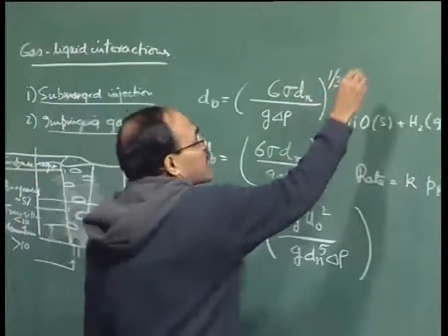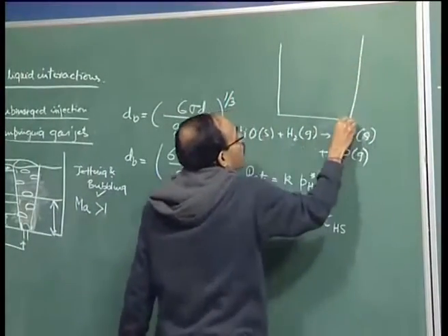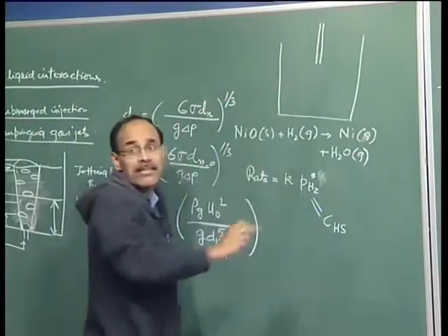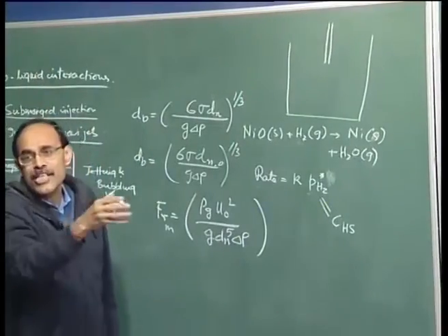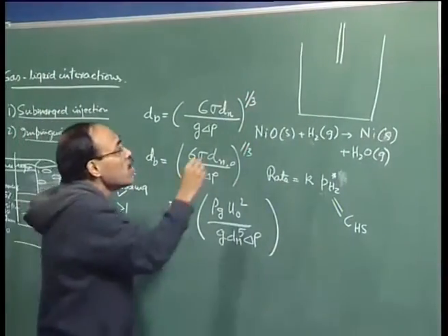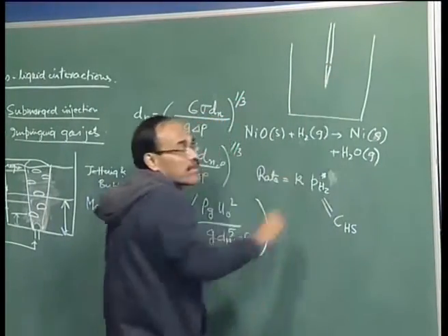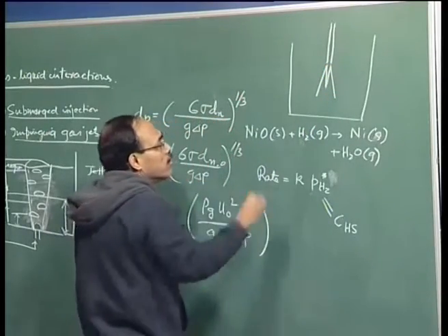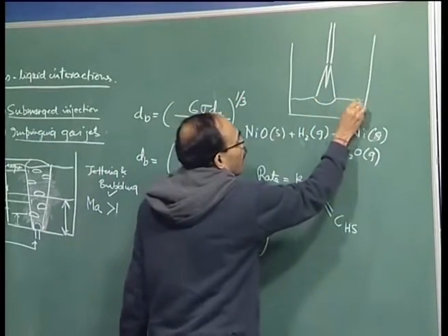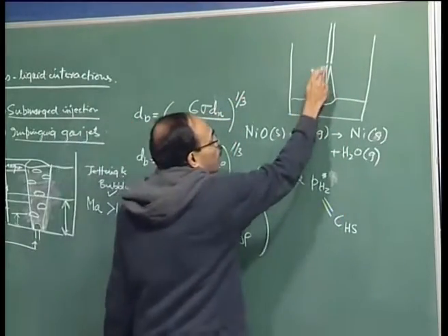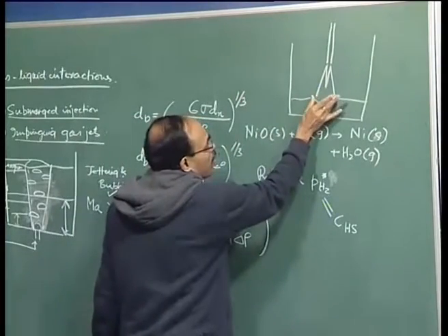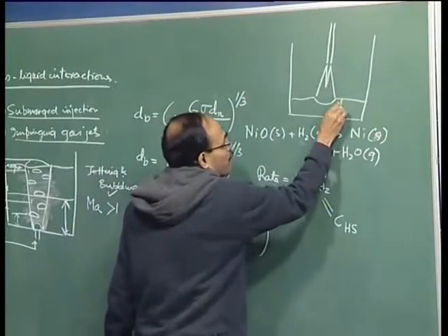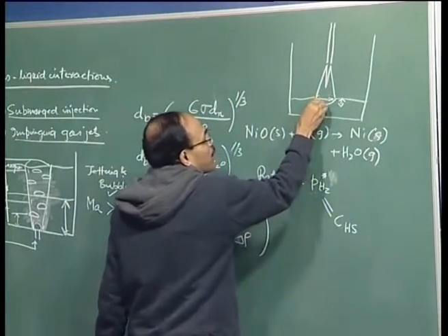Finally, very briefly, about the impinging gas jets. When you have impinging gas jets on a system, particularly an LD converter, you have different kinds of nozzles, such as a tube and then a 6-hole lance or something like that, which distributes the jet onto the molten metal. There is a core of the jet, and following the core you have large scale entrainment, so considerable widening of the jet takes place, and this widening jet ultimately impinges here. By controlling the height of the nozzle, you can control the depth of penetration, as well as the impinging area itself.